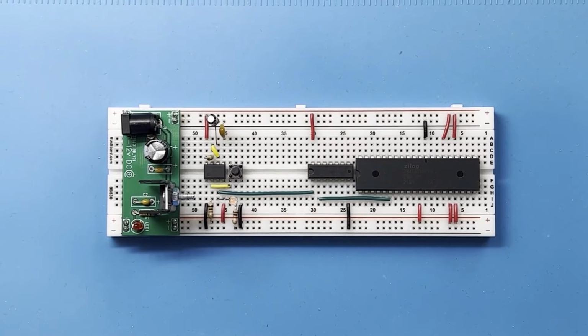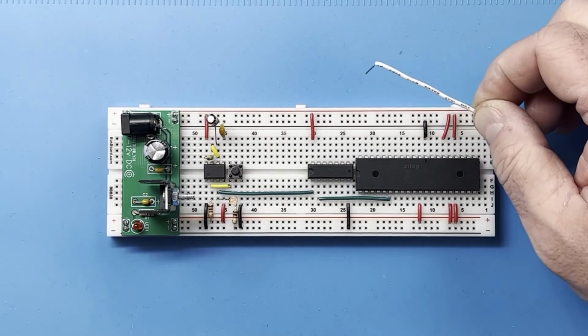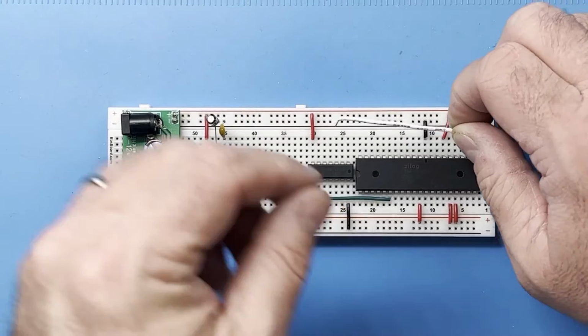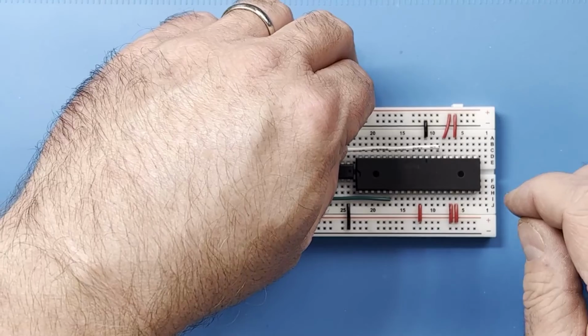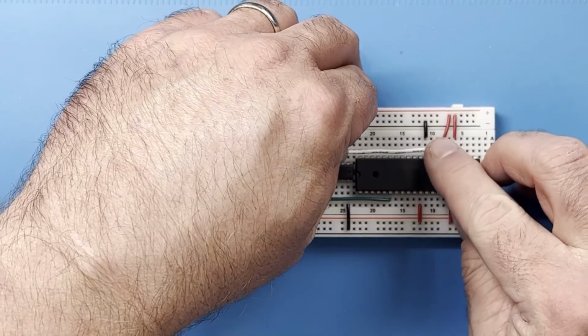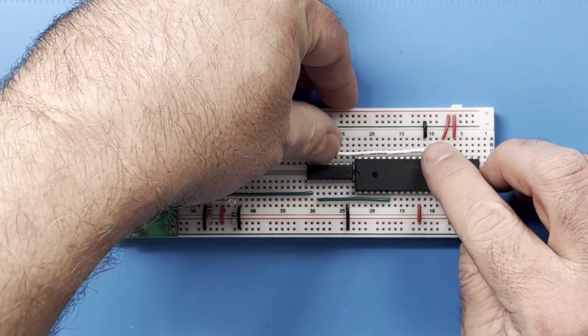All right, now I want to hook up LEDs to the M1, the MEMREQ, and the read pins. This will help us to see what's happening during each T state. Since they're active low, I want to run these through the inverter so the LEDs come on when they're active. So what I'm going to do is connect the M1 pin, that's pin 27, to the first input on the other side of the inverter there, which would be pin 13. So I'm going from 13 to 27 over here, right? Yeah, 26, 27, yes. So that's where that's going.